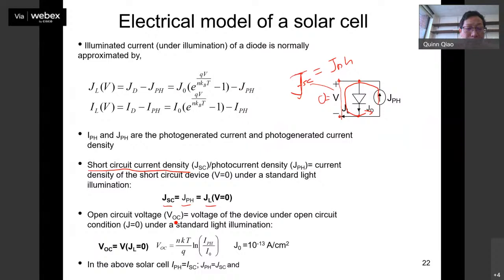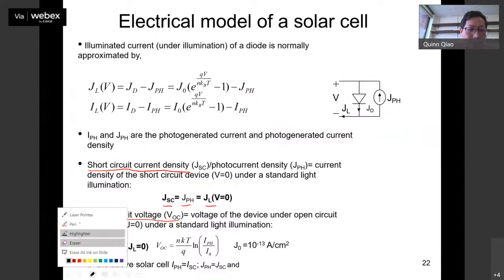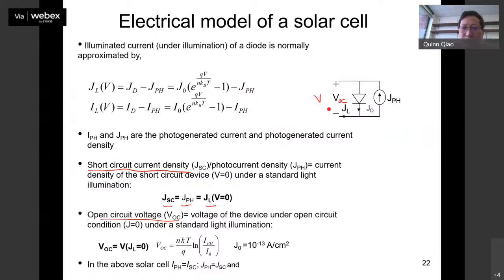And the same thing if you think about the open circuit voltage. Let's think about the open circuit voltage here. When this is open, then you have V_OC here. This is V_OC, and you see there's no current going here. The current has to flow like this. This is the V_OC, and this is also V_OC. Then that V_OC will be equal to V.